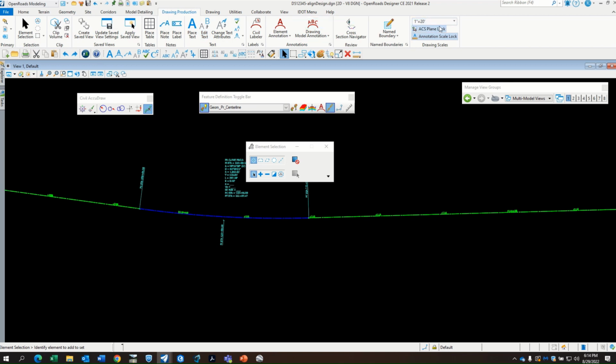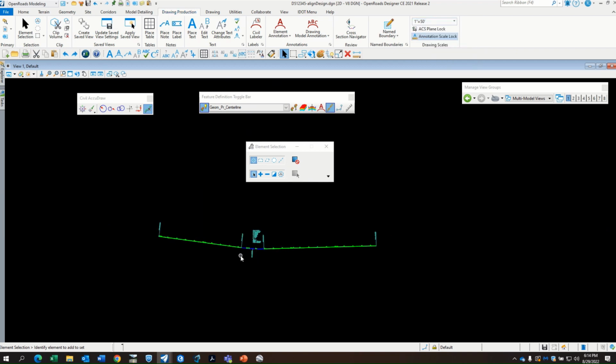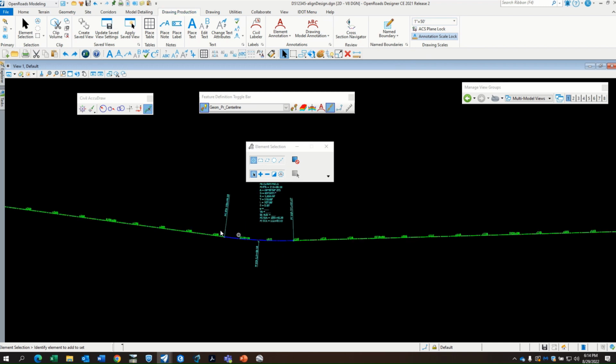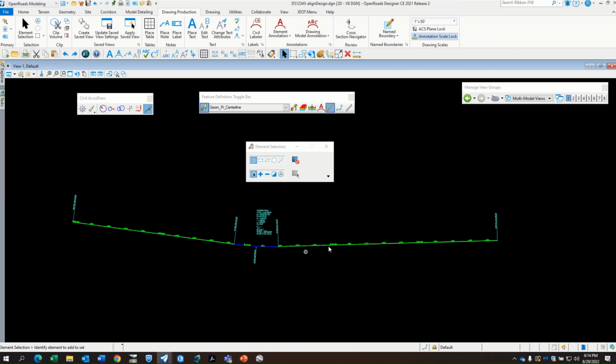My drawing scale is set to 20. This is actually going to be a 50 scale job. I'll go ahead and change just in general working 50 here, even though it's not going to matter on the sheets. This is really design file specific when you change an annotation. So it's saying in this design file it's being visualized as a 50 scale. And that looks good. There's my proposed alignment.